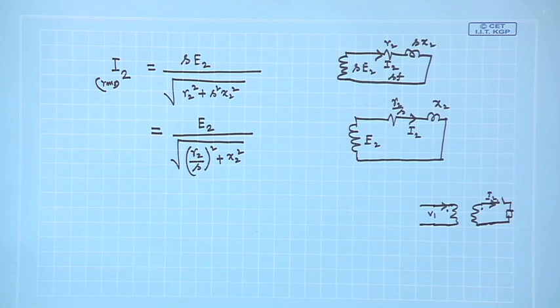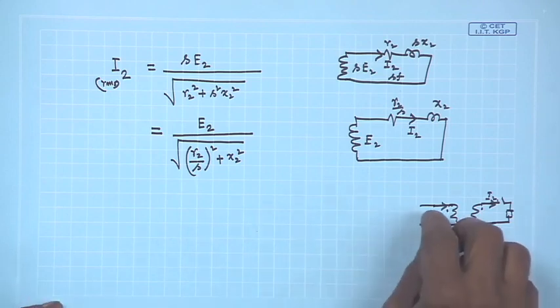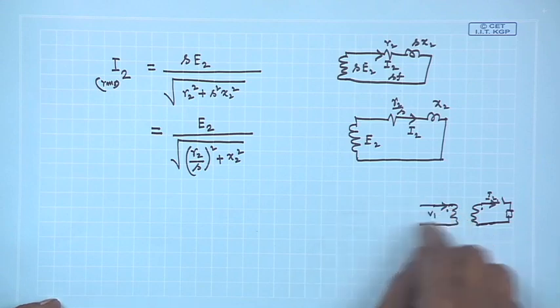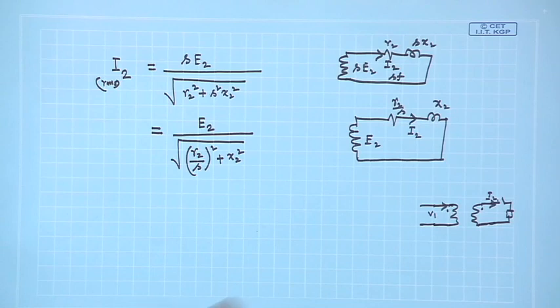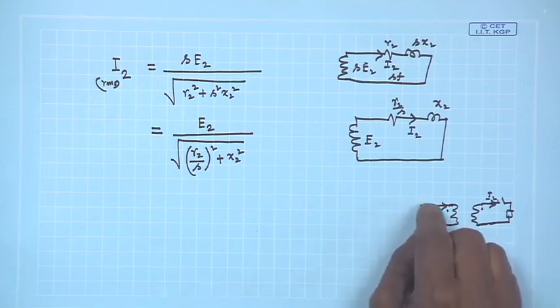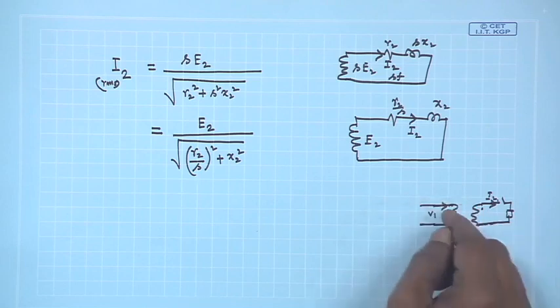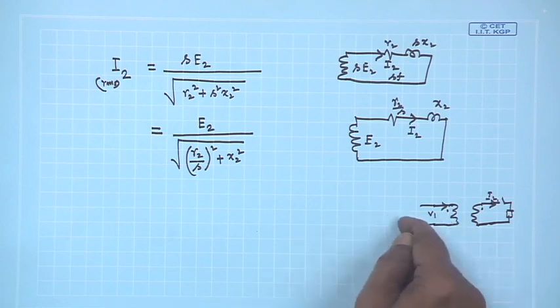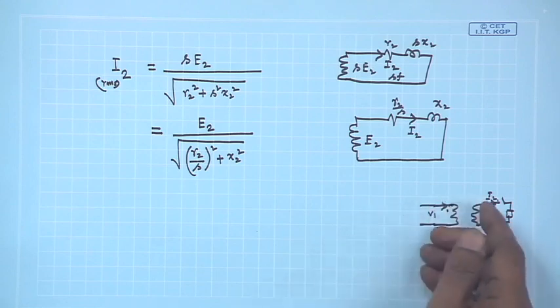Why can that not change? Because the supply voltage, the KVL is to be satisfied here in this winding. Applied voltage, small r1 x1, which suppose you neglect. So the EMF here gets fixed by this V1, nothing doing.